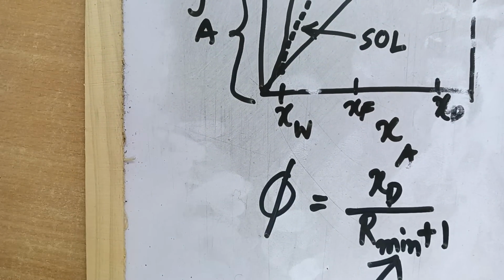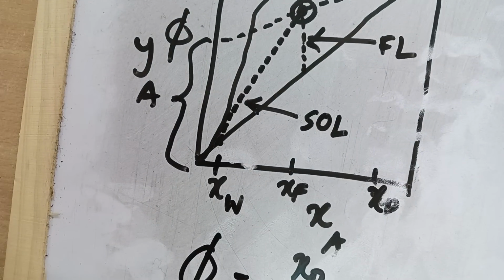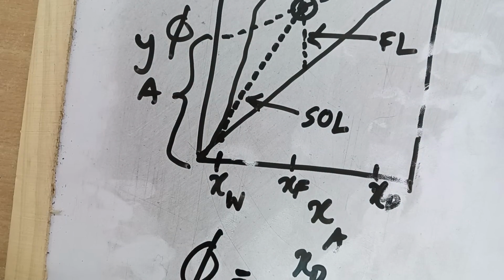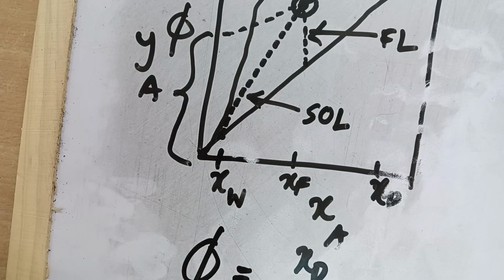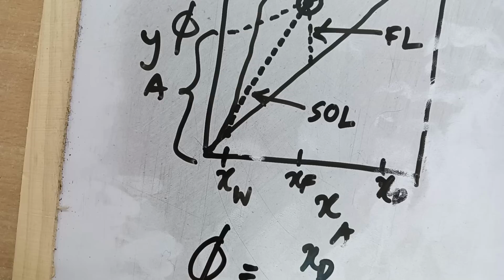So the summary of the whole discussion is that once you have vapor liquid equilibrium data which forms a curvature which is slightly different from the conventional one, which happens to be concave downward, and if you follow the standard method, it's fine. But if the curvature is quite different, as I have just shown you for case 2, and if you follow the standard method, there may be a possibility where the operating line might be crossing over the equilibrium line, which is practically not feasible.